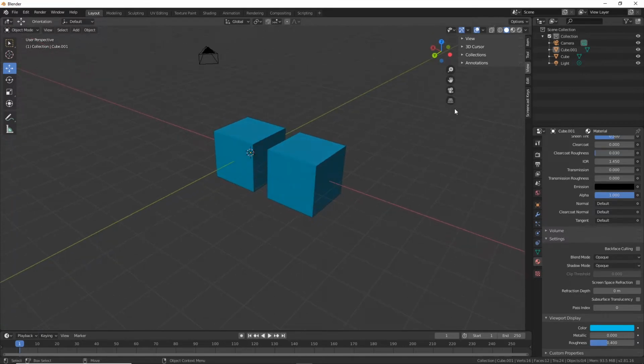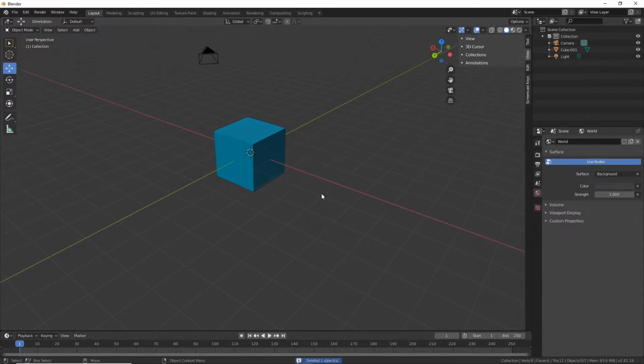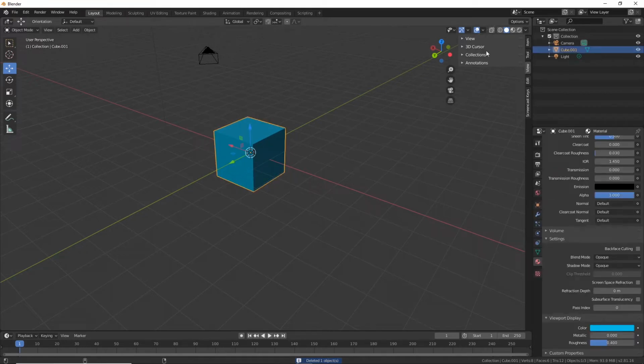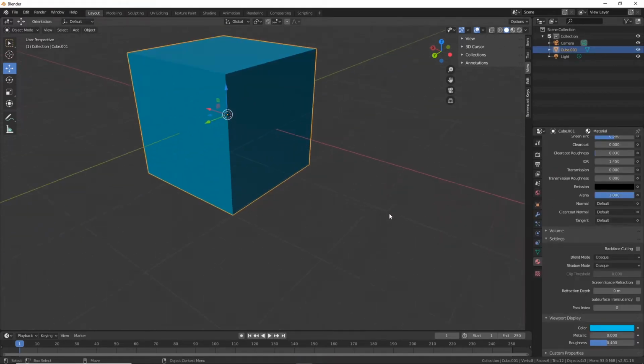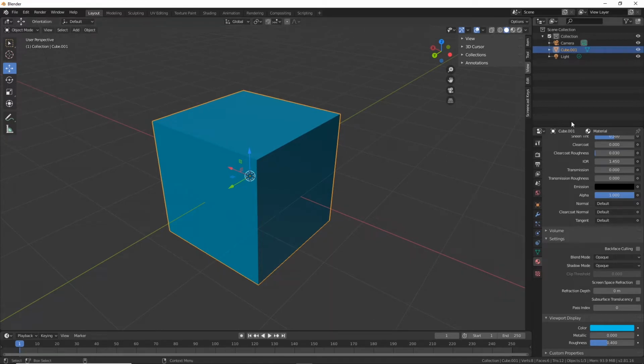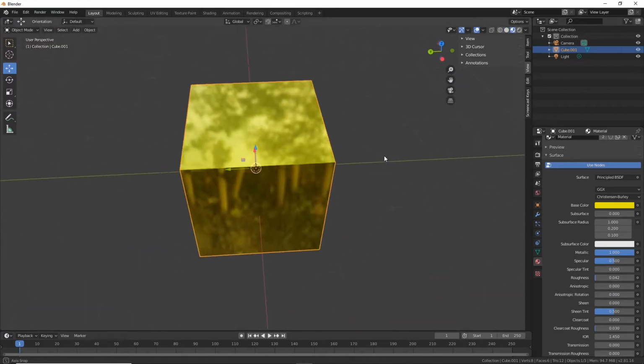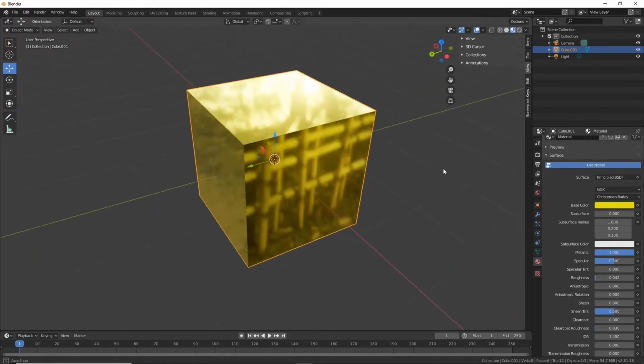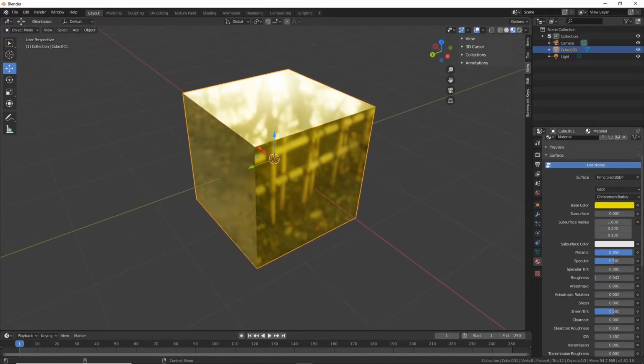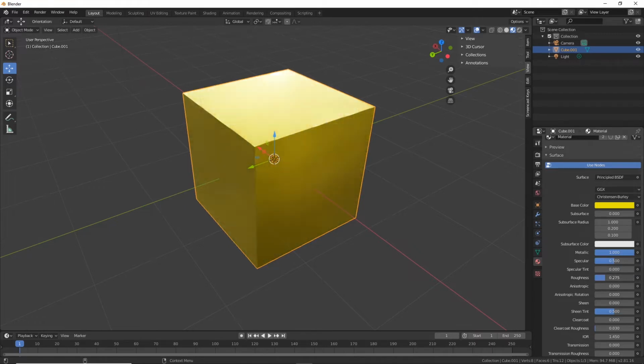more complex scenes, but that gets us into the actual material rendering or shading, which you're not going to see here. So if I'm in just standard shaded mode, notice I don't see the base color. If I make it super metallic and really shiny by cranking the roughness down, nothing changes here. If I go into this, however, now I see that I can actually tweak the material shader. So if I want to make it less metallic, I just slide that, you'll see it in real time. And the same thing with the roughness going both ways.